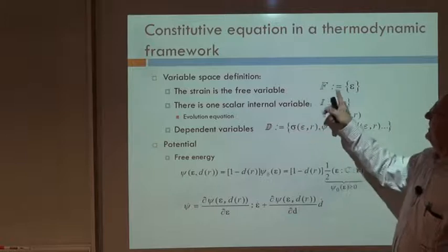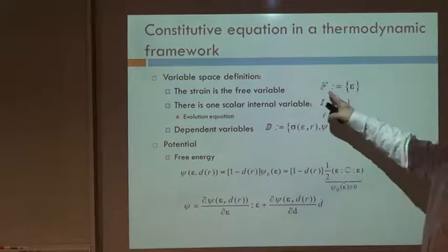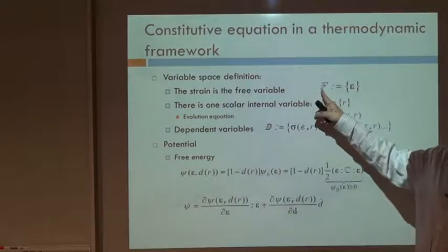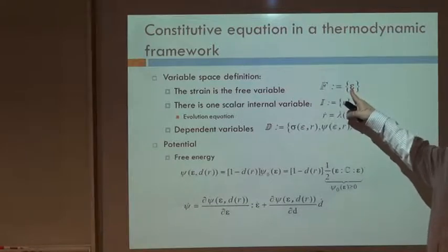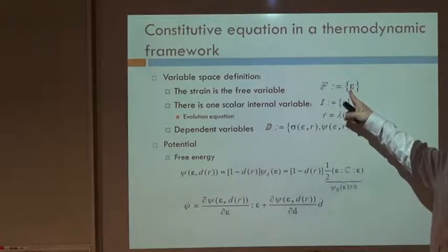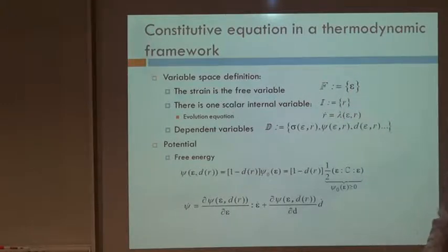First, let's consider a strain-driven problem, which is the most appropriate, I insist, for the type of finite element approaches that we are going to use when we insert this constitutive equation into a finite element, linear general solid mechanics problem. So the free variable set is just 1, the strains. We could have also chosen the stresses, but we choose the strain because it's more convenient.